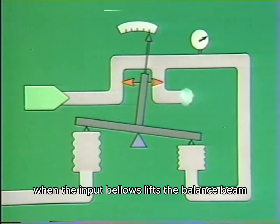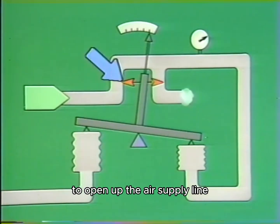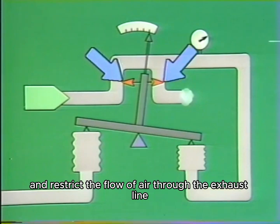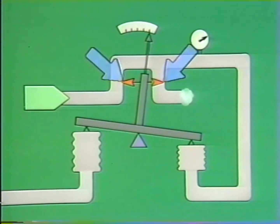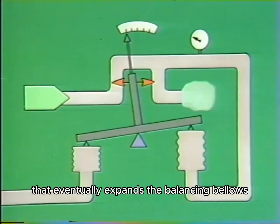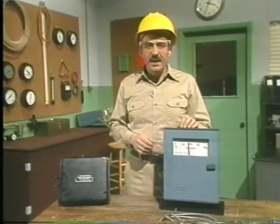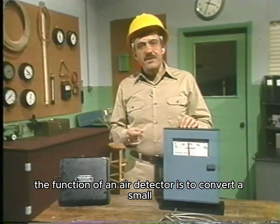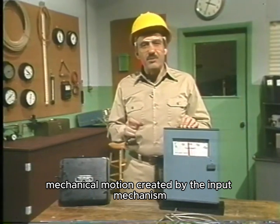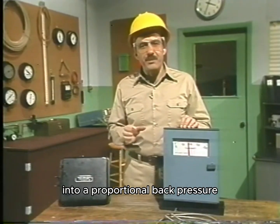When the input bellows lifts the balance beam, it causes the error detector to open up the air supply line and restrict the flow of air through the exhaust line. Restricting the exhaust allows the flow of supply air to build a back pressure that eventually expands the balancing bellows and balances the instrument. The function of an error detector is to convert a small mechanical motion created by the input mechanism into a proportional back pressure.